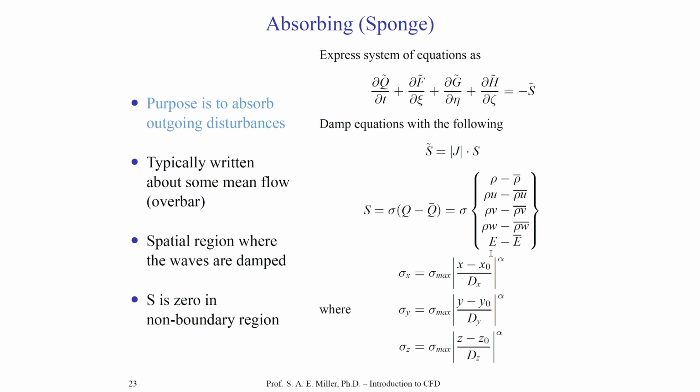So as a disturbance moves through a sponge layer, which is written around the edges of the domain, which we'll show an example of in a second, it will lower the solution through damping from its value towards the ambient value. Now, sigma varies from 0 to 1 from the interior of the sponge to the exterior of the sponge.